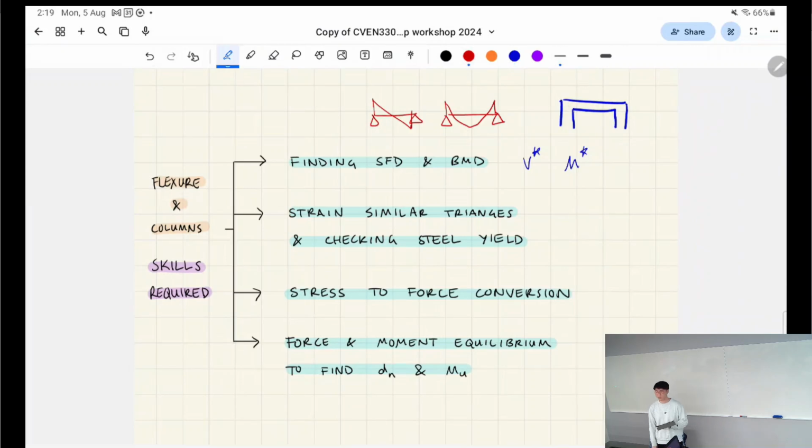I guess just like a rigid beam to column joint, right? So it has a little bit of rigidity, so it has this little jump. It's called a hogging moment in the bending moment diagram. But yeah, this is where your positive moments are, this is where your negative moments are, and so on.